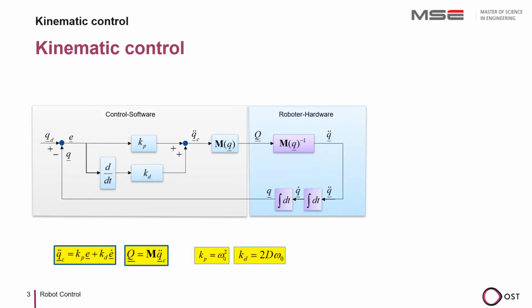In the control system, we now see a much more flexible formulation of the PD controller. The dynamics, and thus the mass matrix of the robot, change constantly, depending on its position. Finding a good control for this variable controlled system would have been a pain. However, since we have now factored out the mass matrix, the most important changes in the robot's dynamics are taken into account in it, and our control becomes simple.